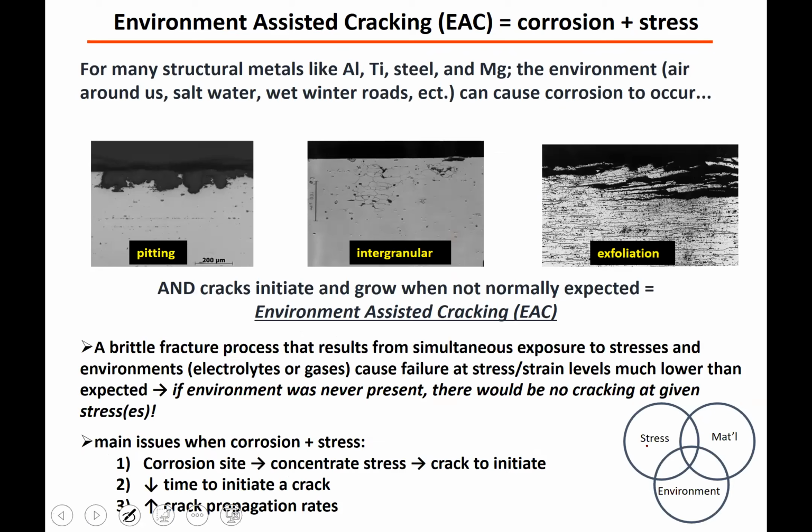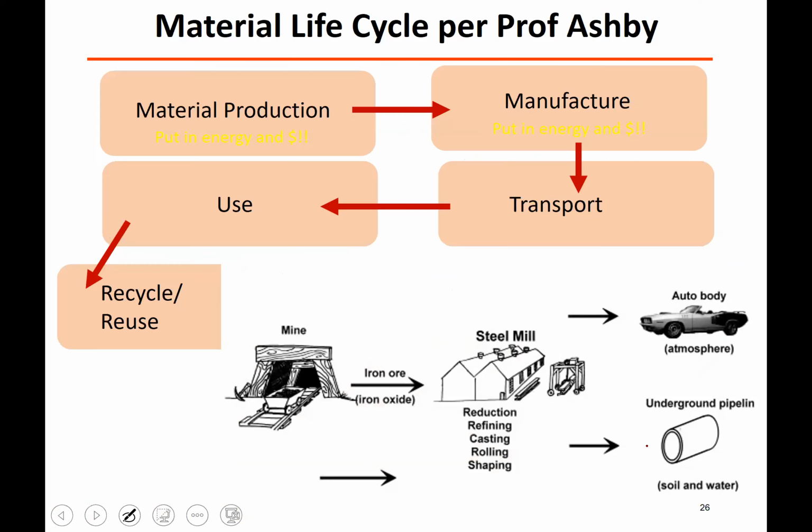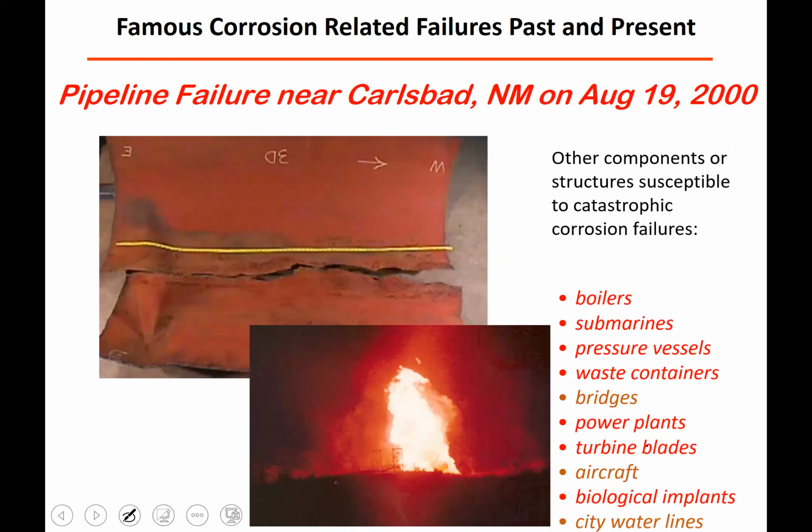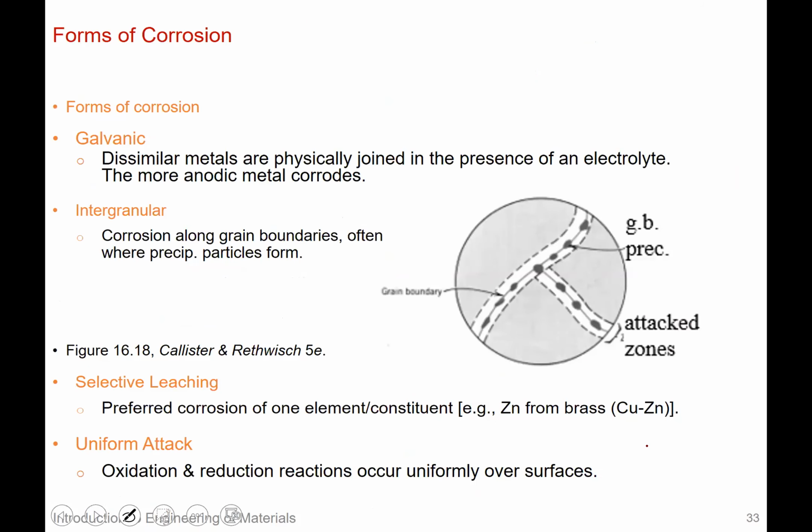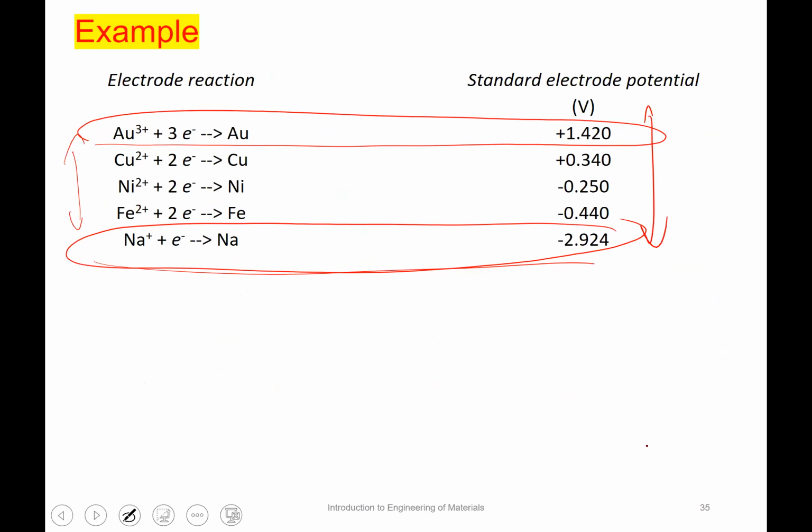So basically just look at and compare the voltages. The example I gave here is obviously just based on thermodynamics, but the methodology is the same. You look at the electrode potential, and the larger the number, positive as well, then that's going to be more noble. And this is going to be more active. Okay.